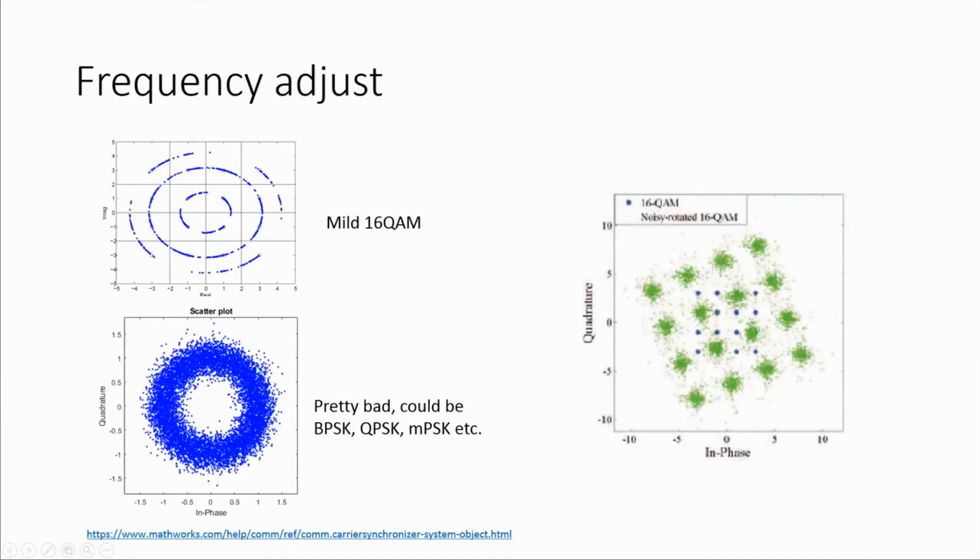And this may only be a few percent, or not even that. The frequency precision of Wi-Fi has to be, I think, less than 50 ppm as a total budget. So that's really, really close. So it's super important to adjust the frequency. If nothing else, we want to stop this constellation from moving in our IQ phase space so that the dots are distinguishable. So after we adjust the frequency, it's still not phase aligned.